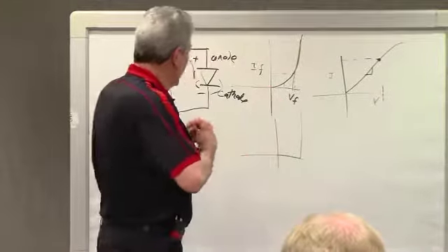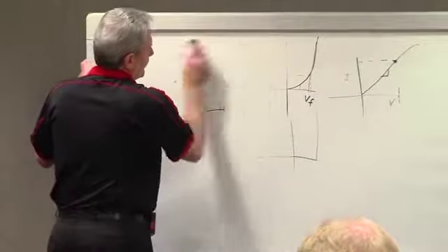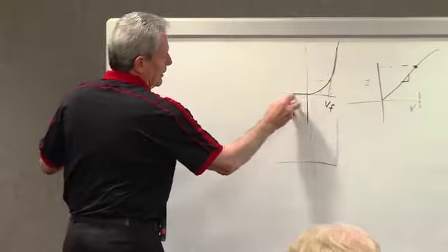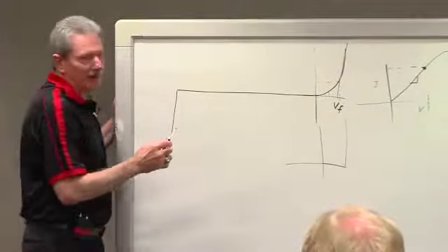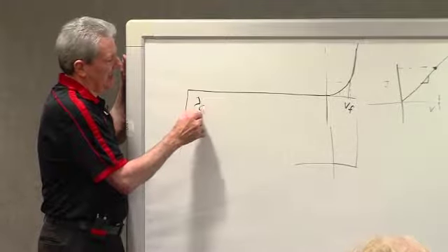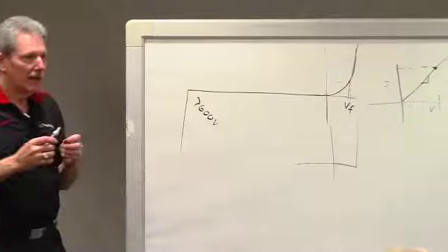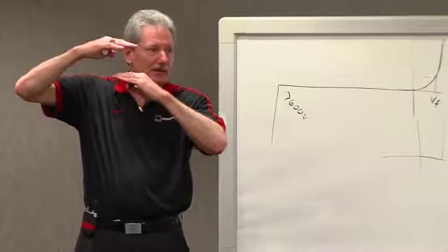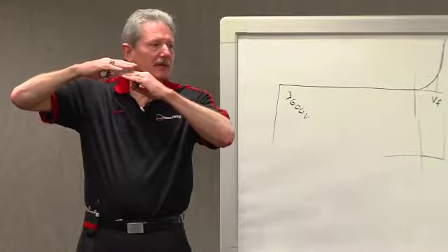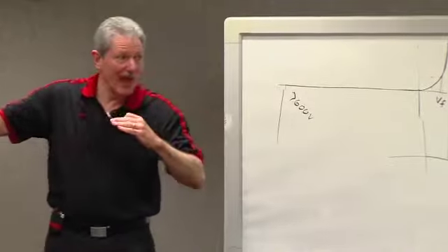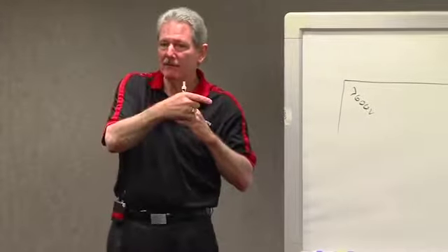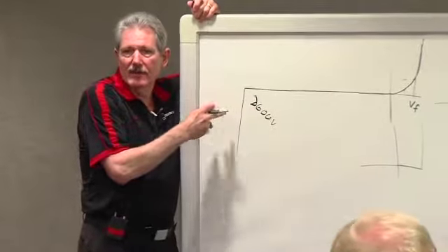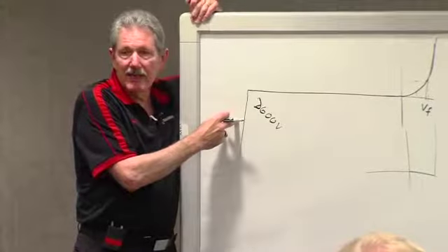There's another feature of this diode. The diode I showed you looks like this, and then at some voltage greater than 600 volts, it breaks down. This junction is very thin. It's a PN junction. It's a thin 10,000th of an inch piece of silicon. So when the back voltage gets so much, it will break that junction over. So when it hits, say, 600 volts, and you're old enough to remember this, where you didn't have Zeners.